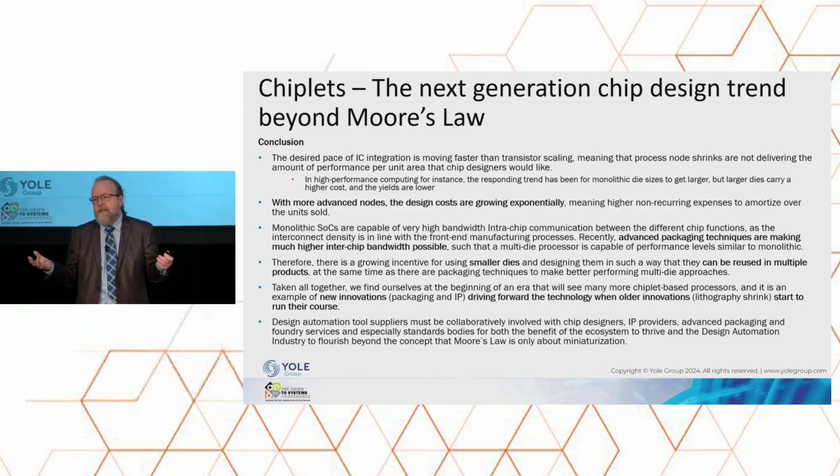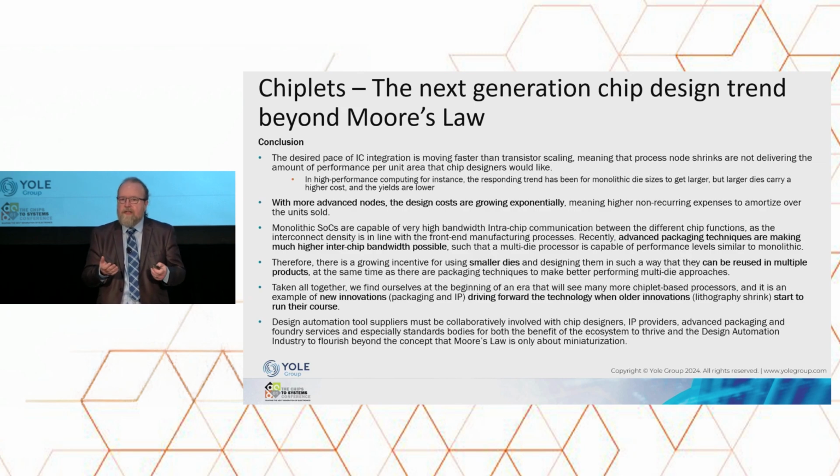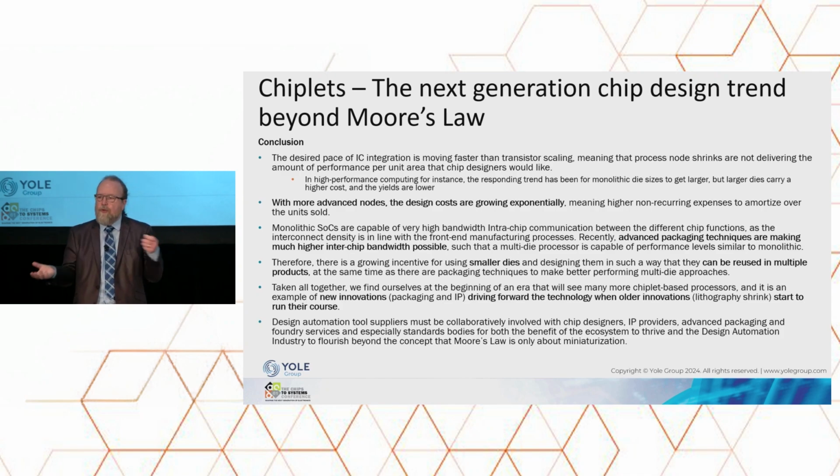Is this going to replace every semiconductor solution? No. As we saw previously, there is a point where monolithic solutions are still the most economical and practical. When you don't have a wide variety of process nodes or functions, and they're in a small package already, there's no reason to add the expense of chiplet-based design. So your tools will definitely need to accommodate both monolithic and chiplet-based designs.